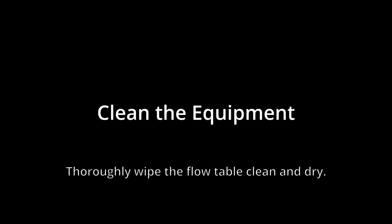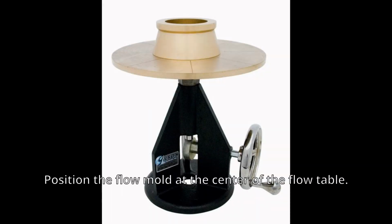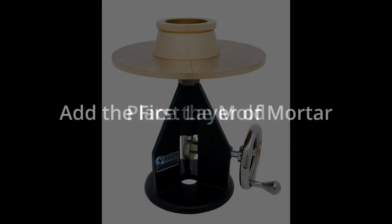Procedure. So the first thing to do is to prepare the cement mortar. Next thing is clean the equipment by thoroughly wiping the flow table clean and dry, ensuring no debris or moisture is left on the surface. Next step is place the mold. Place the mold by positioning the flow mold at the center of the flow table.